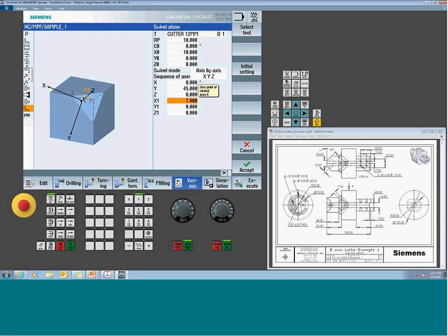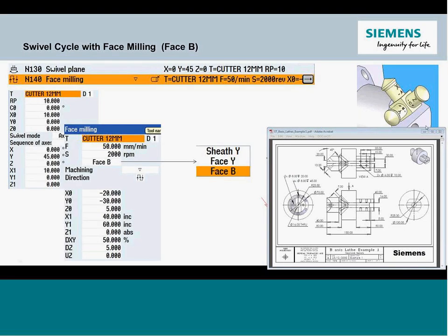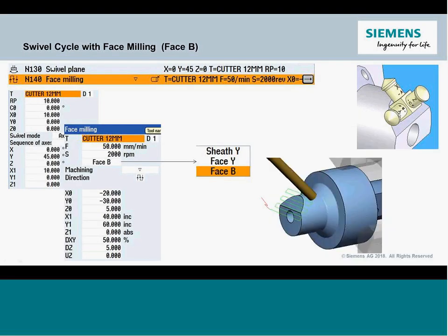And I'll shift in my X 10 millimeters up to the center. Things you want to get your head around once you start programming this method is where's the coordinate system when you're all said and done. Get your hands on a little coordinate cube. They're very, very helpful. At the end of the day, we saw in our previous slide, the system is going to be sitting right here. So up, Y is across the part. X plus is going kind of back towards the chuck.